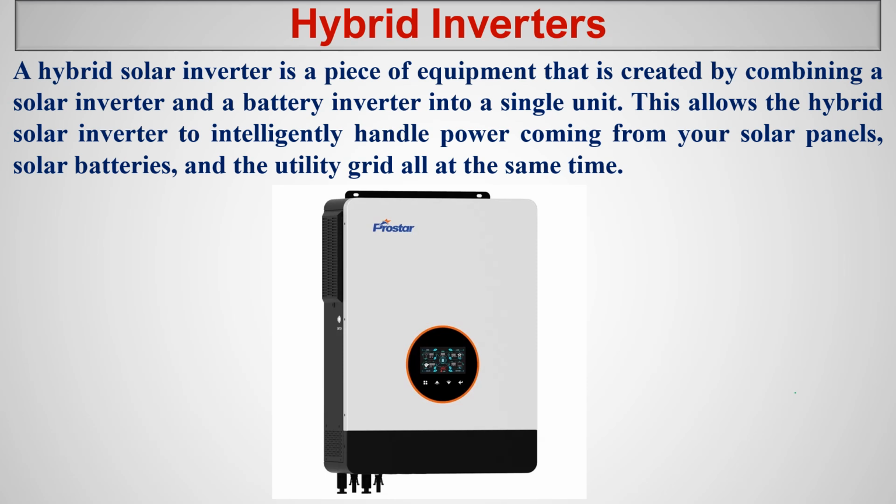So another scenario comes: now I don't want the grid, I want to charge the battery from the solar panels. At that time, the hybrid inverter works as a smart device which works as a charge controller as well, because the charge controller is inbuilt within this hybrid inverter, which is a smart electronic device. Now the DC power from the solar panels will be used to charge the battery. So this is the function of the hybrid inverter.